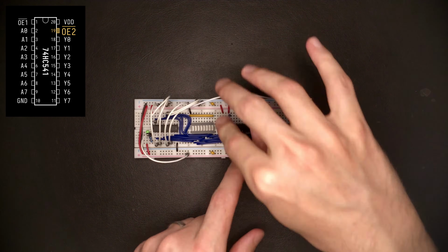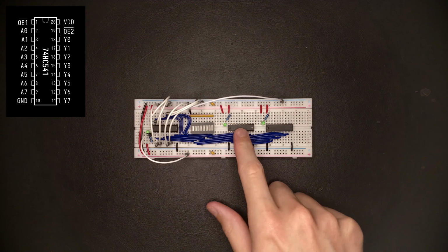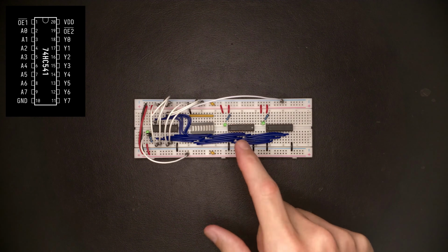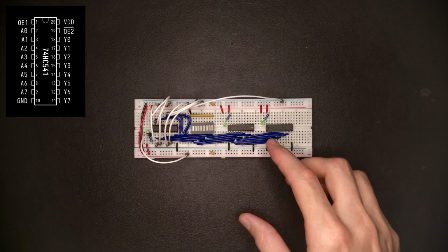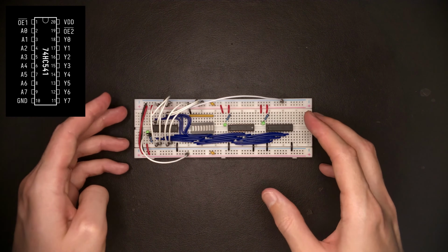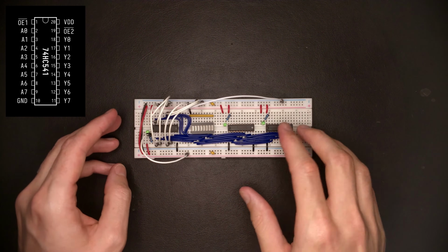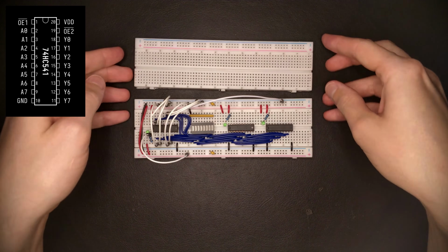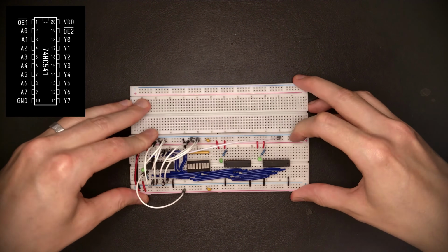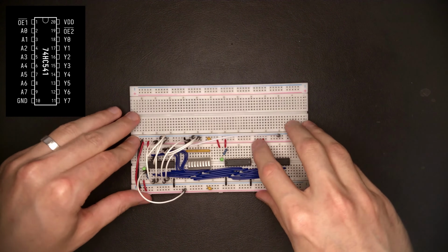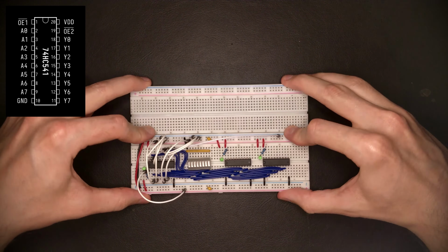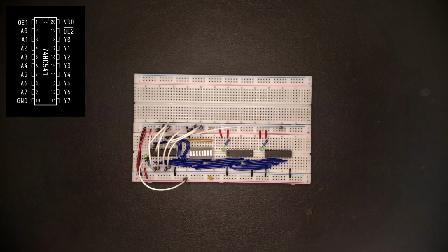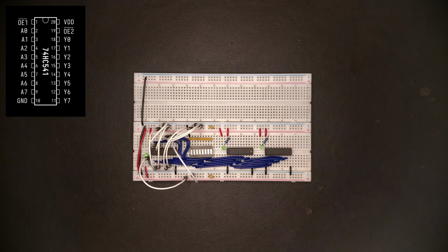Those LEDs need power. Now we'll want a way to look at what the output drivers are producing in terms of data. And in general, we want a way to look at what data goes into the register file and what data comes out of the read ports. So I think what we need is another breadboard on top, which handles the input and output kind of logic and circuitry of the register file. And then we can add bar graph LEDs to that to look at the current state of the read and write data buses. Let me connect the new power rail that we've just added.